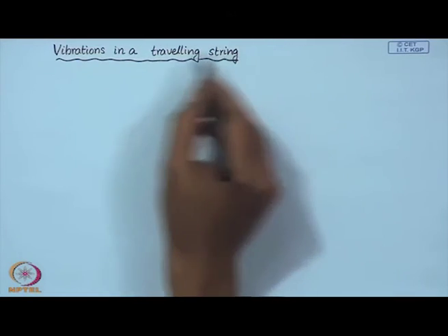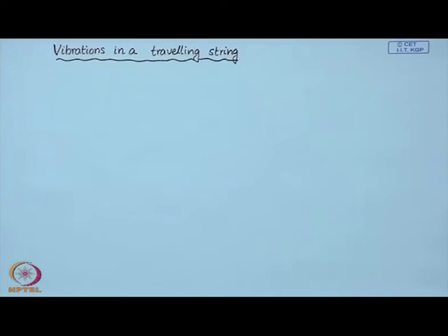We have discussed the traveling string problem before, and the traveling string occurs in a loom or in a rolling mill etcetera. So, we can approximately model a thread line, a traveling thread line, as a traveling string. Now, we are going to look at the wave propagation in a traveling string, how the solution can be represented using these traveling wave solutions, and finally look at scattering of waves in a traveling string.